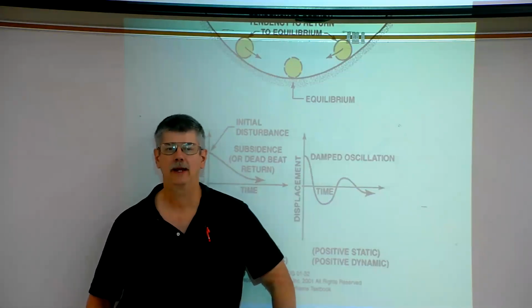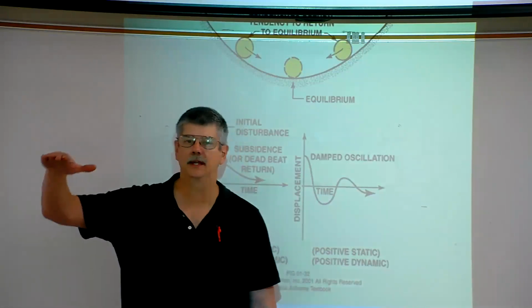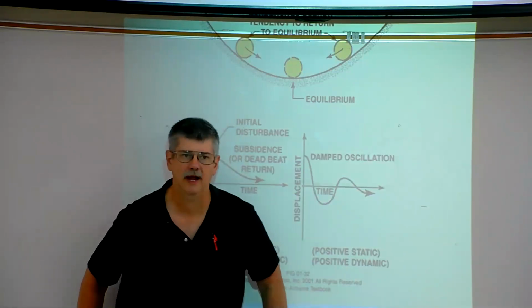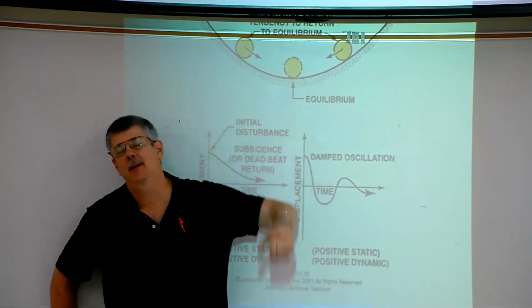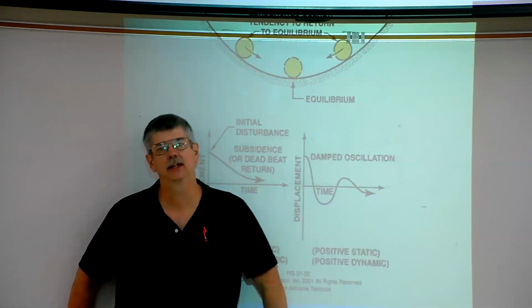The first way is what's known as differential travel, in that the down aileron will travel less than the up aileron. The up aileron will travel a further distance, thus creating more parasitic drag to balance out the induced drag created by the aileron going down.